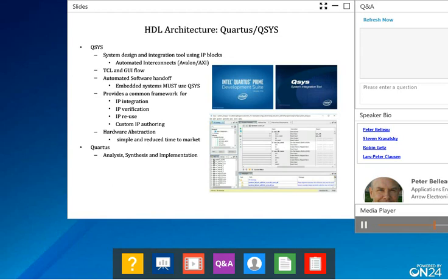The preferred methodology for initially building is to use the Tcl script-driven flow, and this is because it's pretty hard to make any mistakes. It's a reproducible methodology, and you will get good quality results when you build for the first time. After that, if you're a more comfortable advanced user, you can then use GUI tools, but that's the recommended flow when you initially start out.